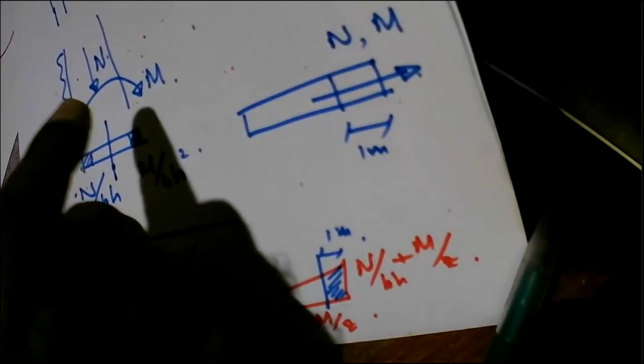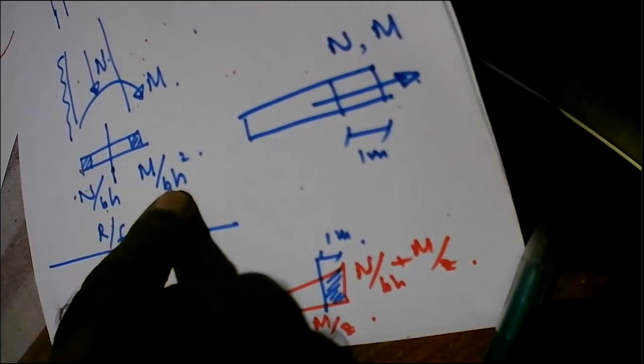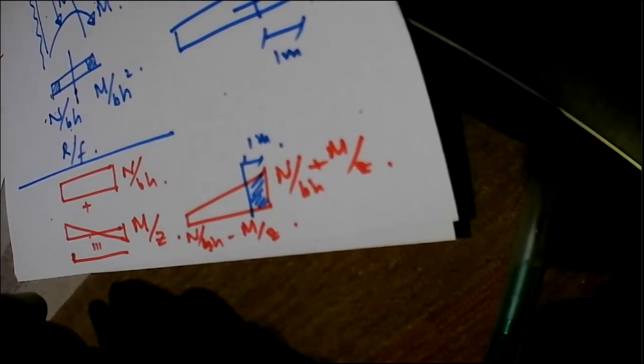So there are two ways of designing a reinforcement in the wall. One method is to consider it as a column and go with the column interaction chart as we discussed last time. The other method is to consider that it behaves like this one, in the elastic range, and find the stress distribution, and then find the corresponding additional moment and consider 1 meter length and decide the reinforcement on a 1 meter length basis, so that you can work out the total amount of reinforcement that you need.